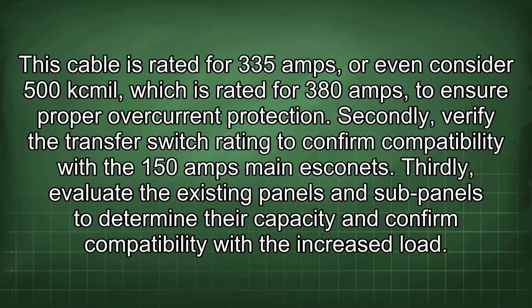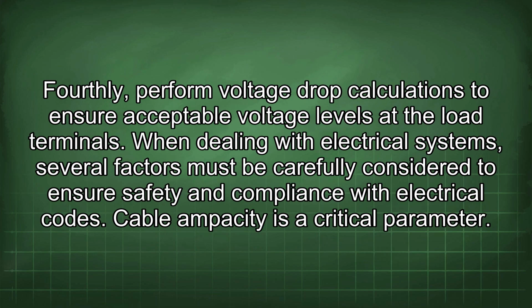Thirdly, evaluate the existing panels and sub-panels to determine their capacity and confirm compatibility with the increased load. Fourthly, perform voltage drop calculations to ensure acceptable voltage levels at the load terminals.